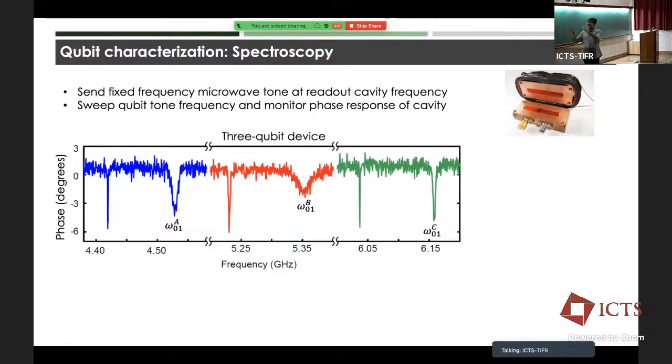This is actually the first way you identify that, okay, are these frequencies in the right place? Because remember that you have to apply the pulses at exactly these frequencies to do any manipulation. What are these other sharp peaks over here? Okay. This first one, the broad one, is the 0-1. These sharp ones turn out to be 2 photon transitions from 0 to 2. So they are actually at half the frequency of this difference, which is why they are close to omega 0, 1, because this is a nearly harmonic ladder. Remember, it's only weakly anharmonic.